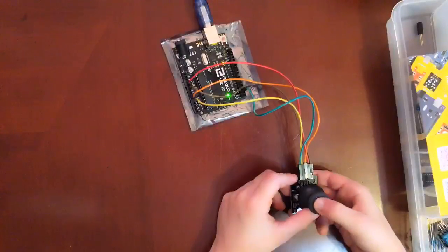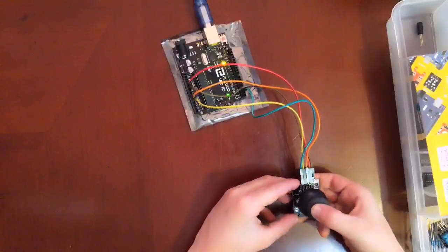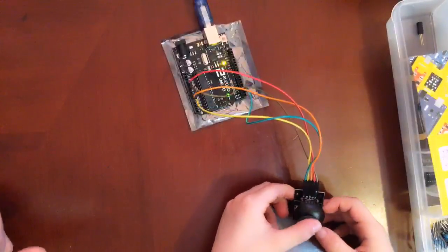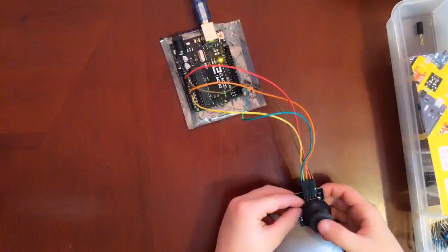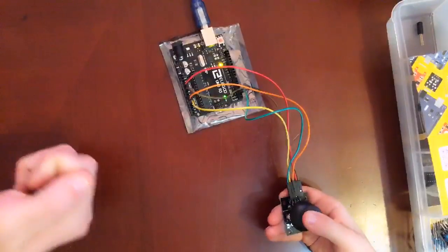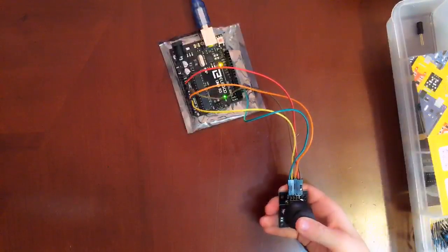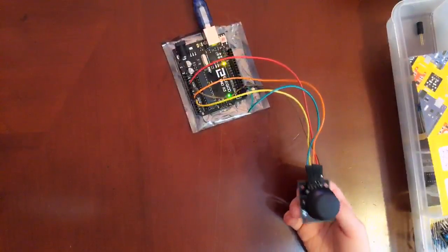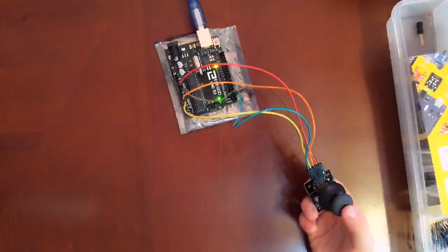Press the button. Okay, it's doing something, see? It's showing 0 right now. Press it again. It could be reading super fast, like press and hold it. See how it's 0, 0, 0, 0, 0, 0. Let go. Now it's 1, 1, 1, 1, 1, 1. So when the button's being pressed, that equals 0. When it's not being pressed, that equals 1. That's what these codes mean, okay?